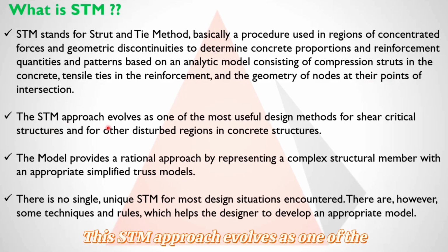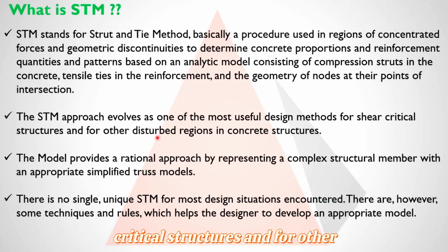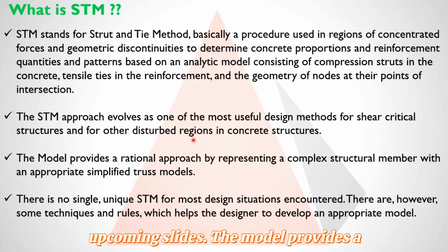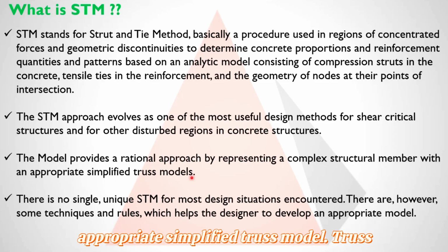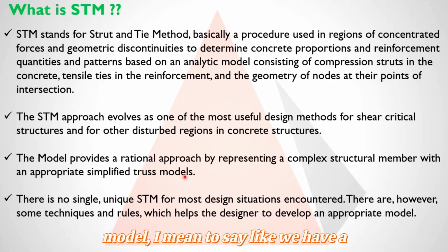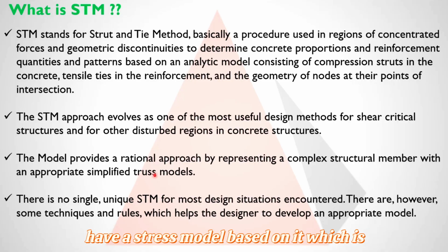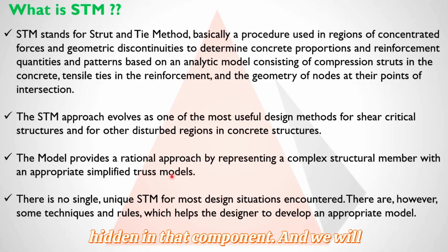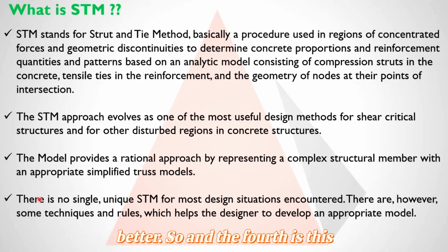This STM approach has evolved as one of the most useful design methods for shear critical structures and for other disturbed regions in concrete structures. We will learn more about this in our upcoming slides. The model provides a rational approach by representing a complex structural member with an appropriate simplified truss model. I mean, we have a structural member, a pier cap or pile cap, and then we will have a truss model based on it, which is hidden in that component. We will see some images, then you will understand better.